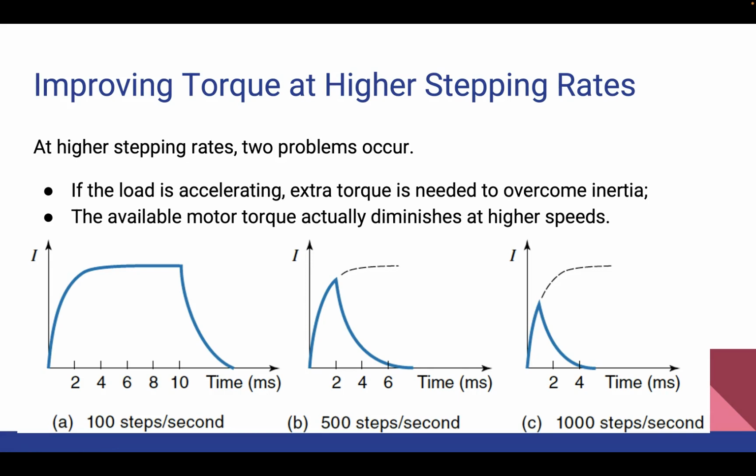And this is very problematic because when steps are missed, the control loses track of the load's exact position, and potentially it can render the system useless. So it's important to remember that motor torque is directly proportional to motor current.